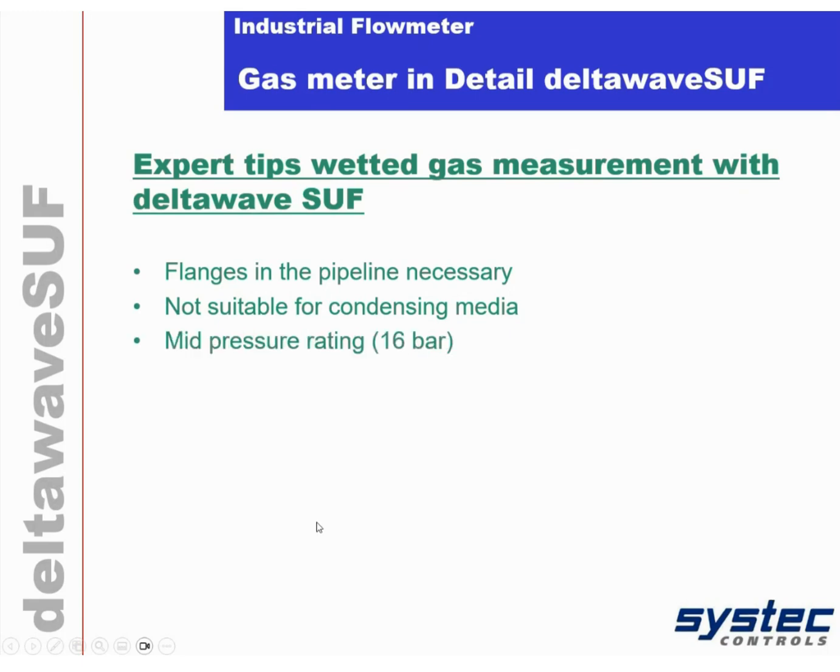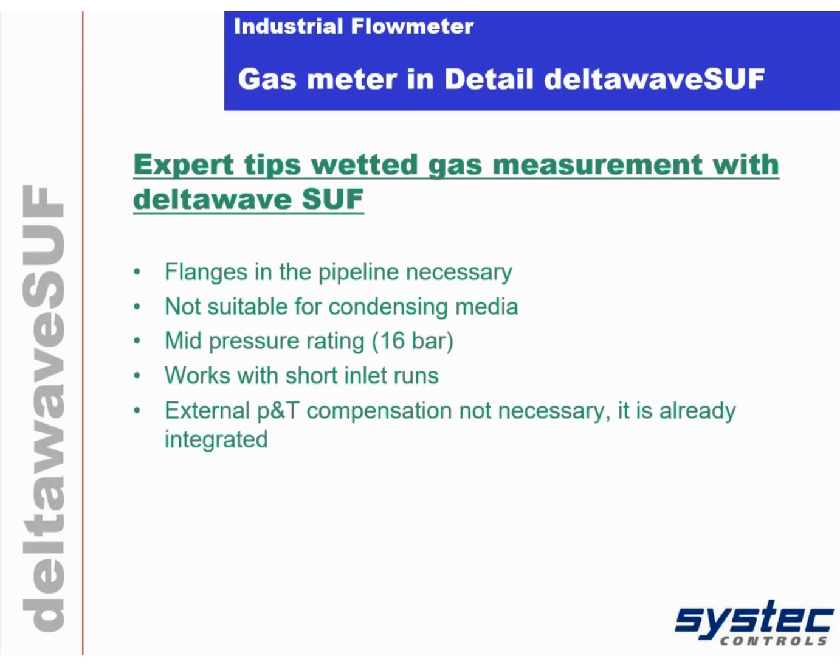The SUF is designed for mid-pressure rating, so 16 bars typically. It works with short inlet, which is very nice. External pressure and temperature compensation is not necessary. It's already integrated. You can operate it by battery, which is also good.